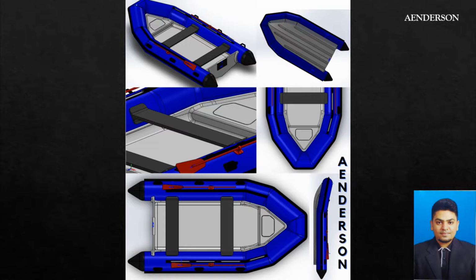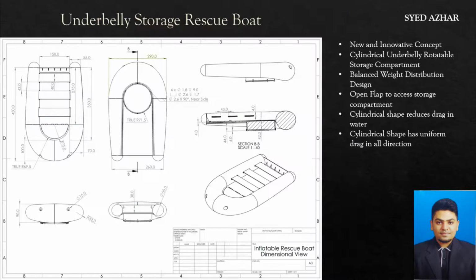The next design is made by me, Syed Azhar. This is a new and innovative concept where the boat features a cylindrical underbelly rotatable storage compartment. Special care is taken to balance the weight distribution, to balance the weight of the large storage compartment in front and the passengers who sit in the middle and back section. The compensation is done by making the front inflatable section much larger, therefore more buoyant, to handle the extra weight in front.